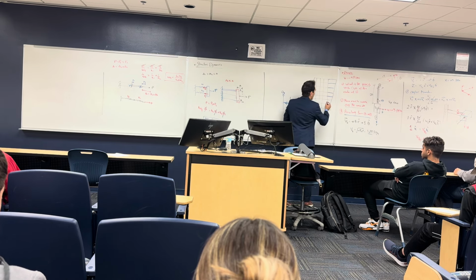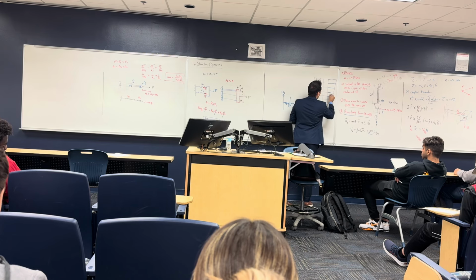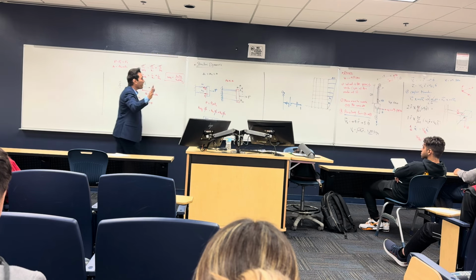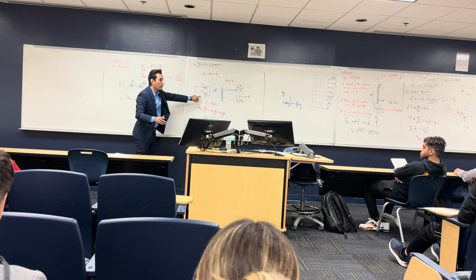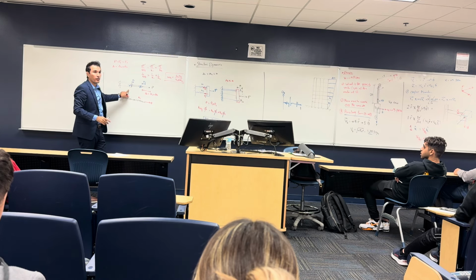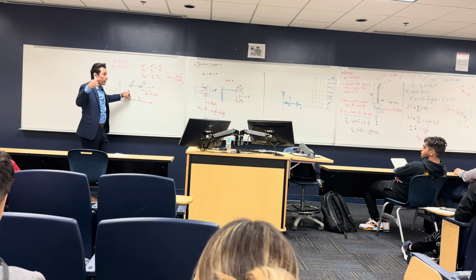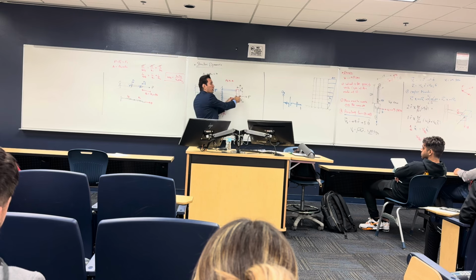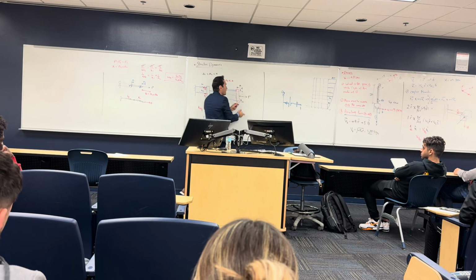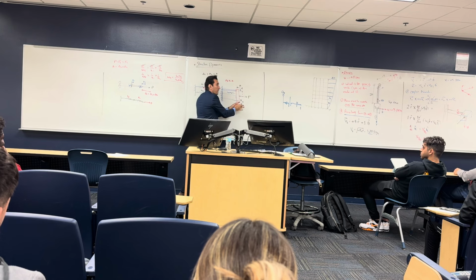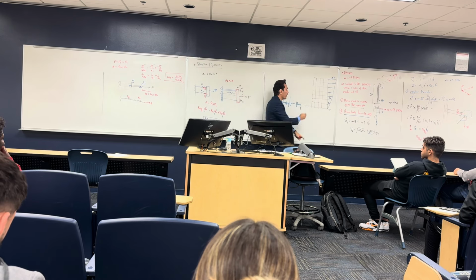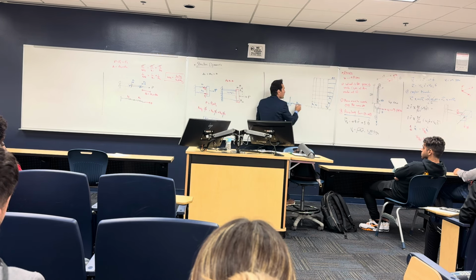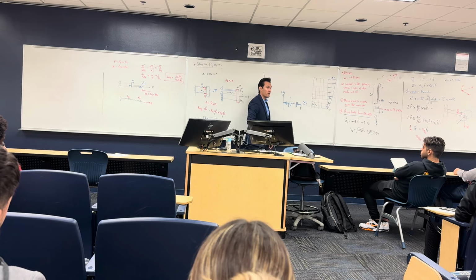So let's say here, delta 1, delta 2, going up until delta n. All of them have the same delta. What this means is that it is a parallel system. Just think of a barrel. Why? Because the two springs here have the same delta. I have a rigid body that takes all of them, delta 1 and delta 2, and doesn't leave any. If I have another spring here, it's going to have the same delta. So all these columns are in parallel. If this column has a stiffness K1, K2, up to Kn, then the whole stiffness of the story is going to be the sum of all the K's in the story.